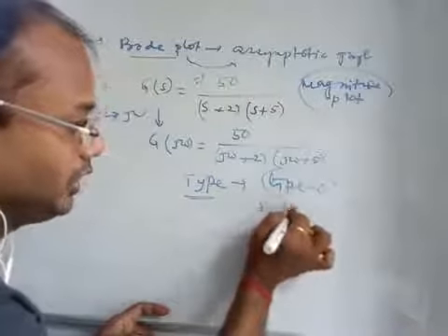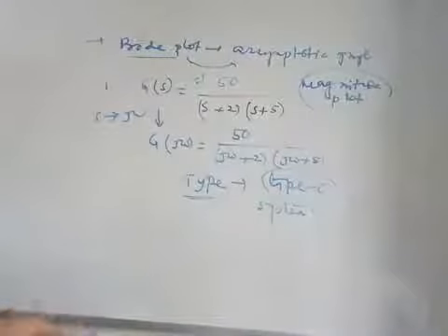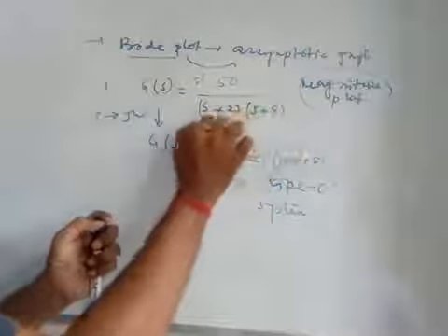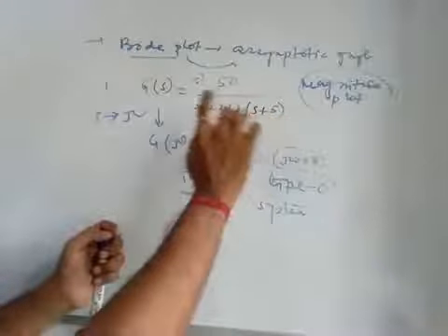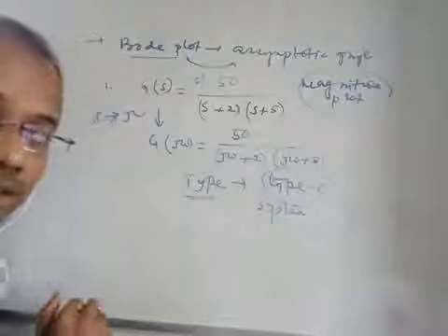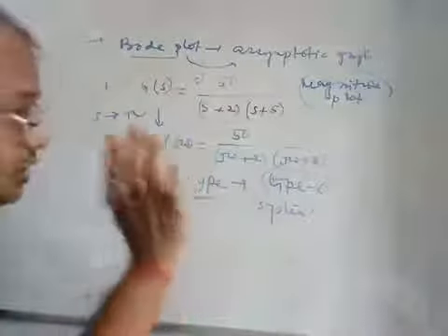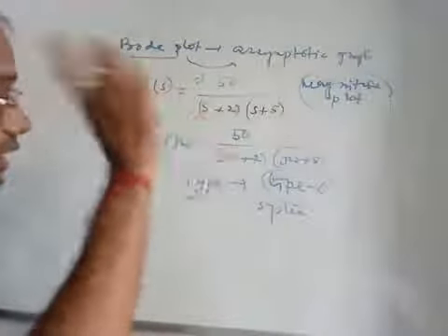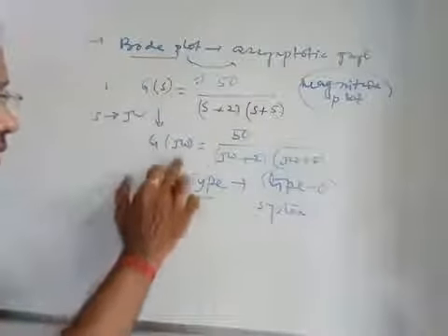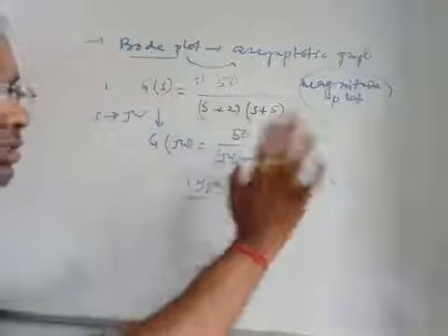So what we have done till now, we have considered a system which has first order factors only. First of all, there are two poles which are lying on the left hand side of the S-plane. That means the minimum phase system. The concept of minimum phase is now clear. Now we have to get the sinusoidal transfer function, that is G(j omega) equal to 50 by (j omega plus 2) into (j omega plus 5).